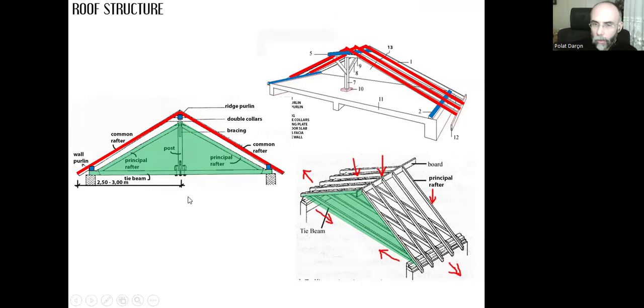And all the loads of the rafters and the above layers, obviously, the roof, all the loads of the roof will be transferred to the rafters, and the rafters, the purlins, sorry, the purlins will transfer the loads directly to the truss. In normal conditions, when we apply the loads over the truss, it can transfer the loads to these surfaces.